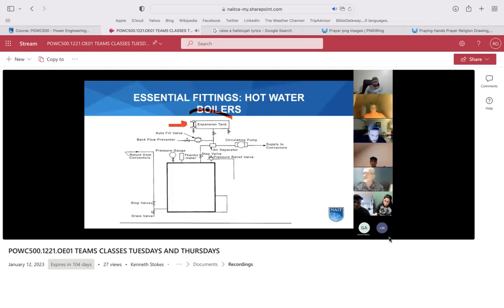So it's generally sitting above the boiler, has the gauge glass, has a drain, might have a vent, probably has a vent, but the vent is normally closed for operation because we want partial air and partial water in that expansion tank. Here's something else you'll see on a hot water system you won't see on a steam system. Steam will push itself down the line, and hot water needs to be pumped and circulated.